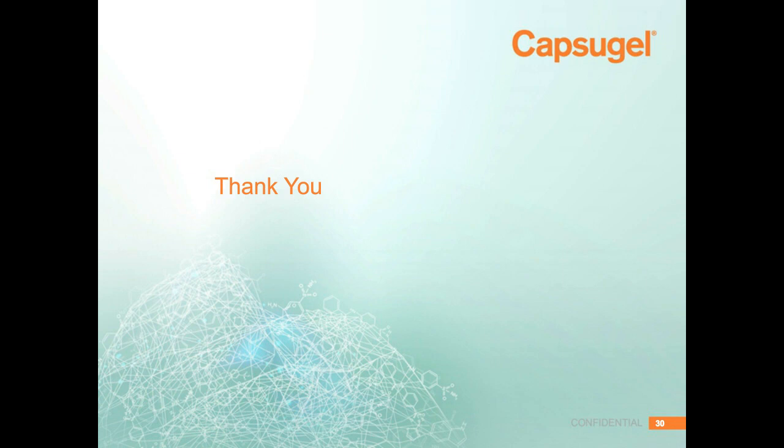But in between runs, especially when you're doing an early feasibility study, you want to clean in between the spray dryer because you don't want to have any carryover, and there can be carryover in between each spray. So I would say certainly yes, you take extra precautions in making sure that you're not having residuals or things like that within the spray dryer and impacting the integrity of your product.